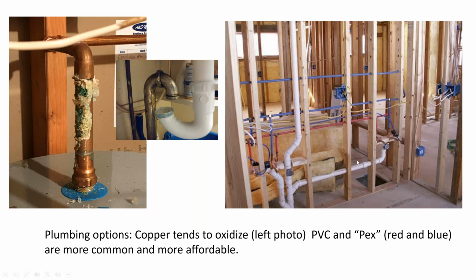Sometimes when drains get clogged, it's because the vent got clogged. Sometimes in new construction, they forget to take the cap off of these when they install them on the roof, and they move in and the plumbing doesn't work. All you got to do is uncap the vent and everything should work fine. It's happened.